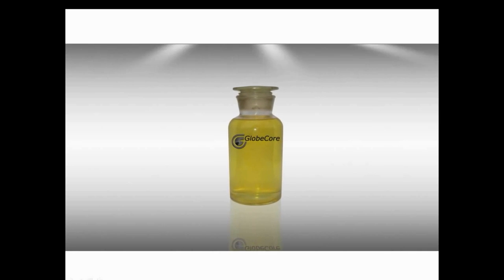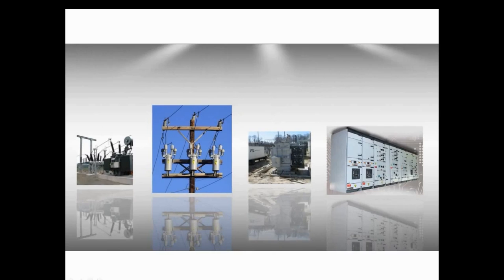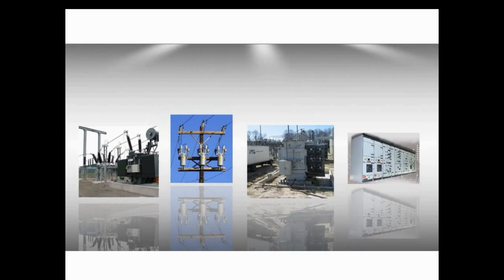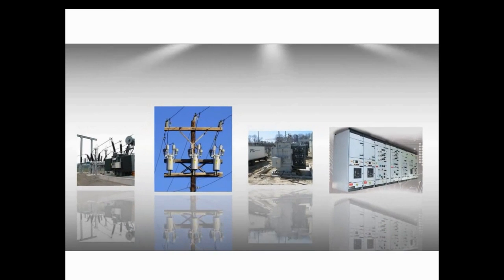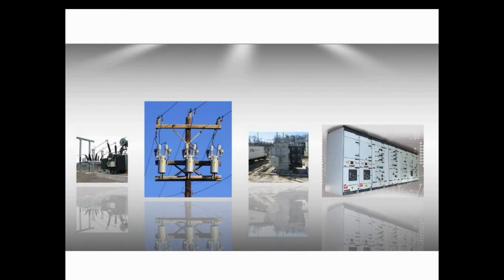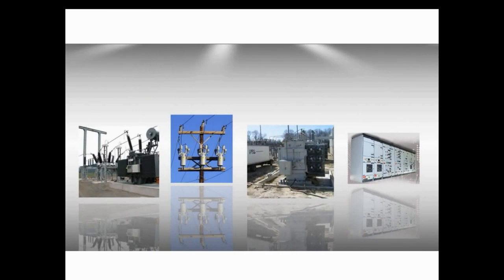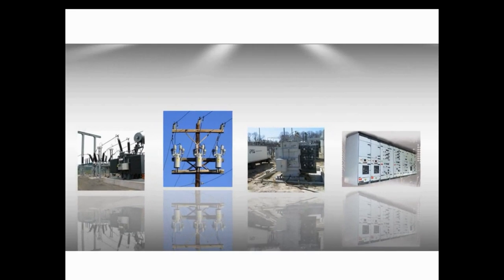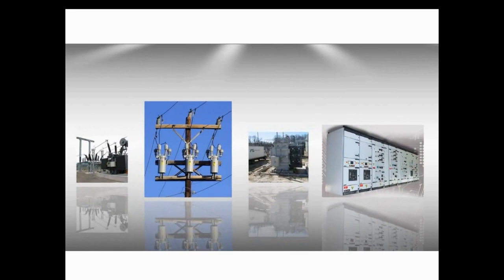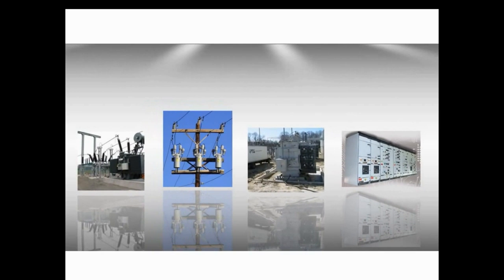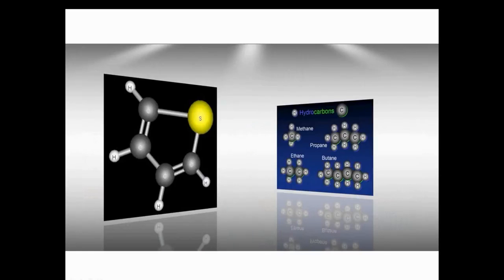Transformer oil is a mineral insulating oil. Except for transformers, it is used in tap changers, reclosers, bushings, and switchgears. There are naphthenic and paraffin oils, and as naphthenic oils are running out, paraffin oils come into usage due to developed refining techniques. Moving to oil chemistry, it's worth stressing that oil is a very complicated structure.